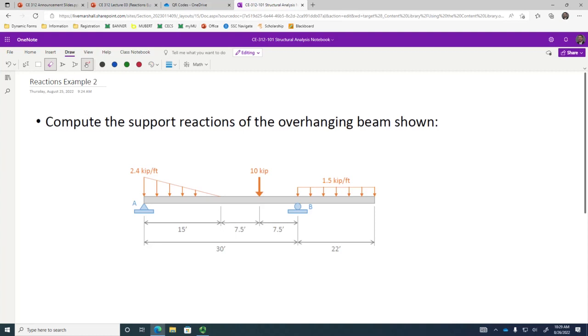All right. Okay, so while you all are writing that, let's identify some of our reactions. So I'm going to go ahead and assume vertical reactions across the board. So we'll call this By and Ay. I will say this, for some of the problems later, it's going to be really tough to guess whether the reactions are up or down. Like right now, I think it's for the most part pretty easy, but it's going to get weird later.